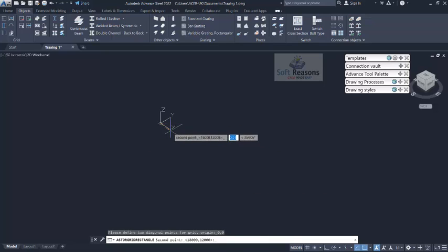So you move your mouse pointer towards the x direction, and then you activate the auto mode right there. So you key in 20,000 right there. Okay, so this is 20,000. You have to use comma on the keyboard. Do not enter. All right, use comma on the keyboard.